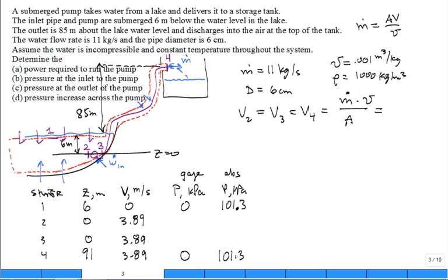For this control volume, if I do an energy balance for this large control volume, I'll have W dot coming in, and notice that I abandoned the sign convention with my illustration. It's into the control volume. I'm putting it in as a positive. I don't like a lot of negatives. All right. It is equal to the mass flow rate times the enthalpy, H4 minus H1.